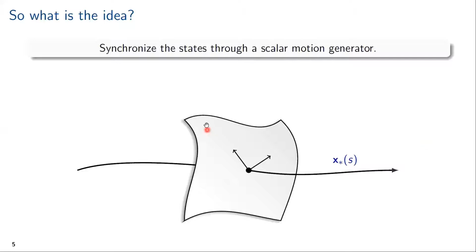For instance, if the states are up here, then we can recover the corresponding s, which would be the point here along this nominal solution, and then we can measure the distance from the nominal solution back up to the current states. And if we can design a controller which for any such perturbed states can enforce contraction, such that if we start here, then we will move towards the nominal trajectory as s moves in time, then we can also design controllers using these types of schemes. So it's useful both in terms of the planning and in terms of control design.